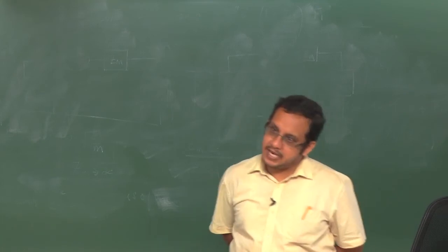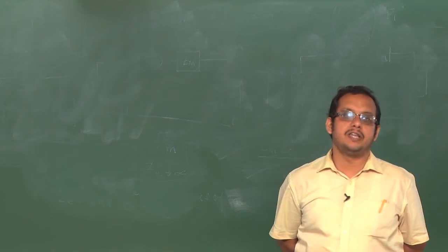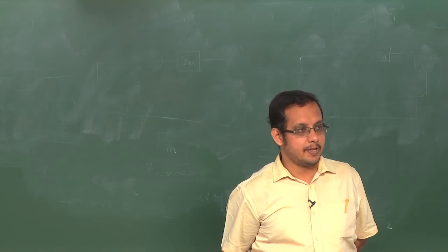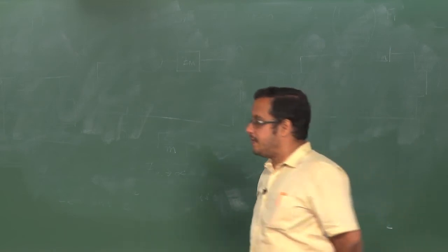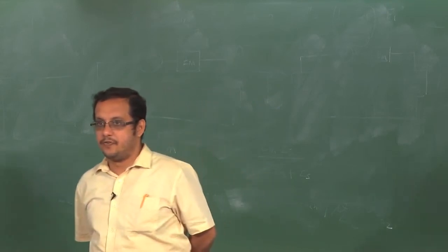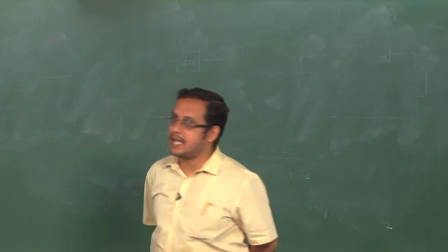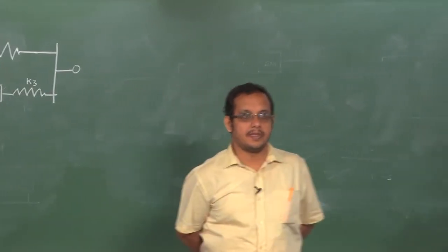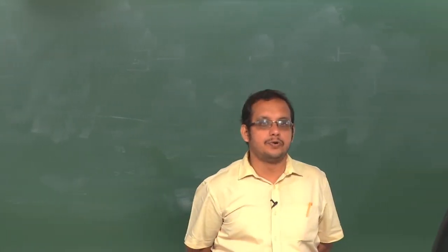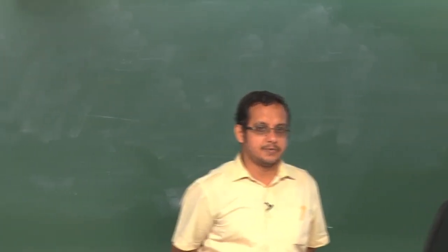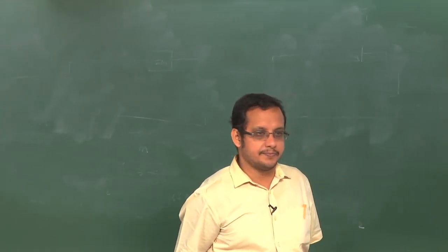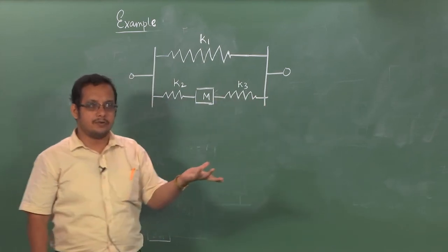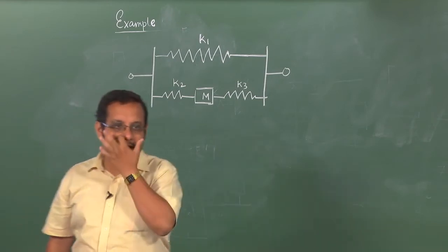If it was placed in line, then the forces between the input and the output port are possibly different, but the velocities are the same, right. And if it is in shunt position, the velocities are possibly different, but the forces are the same. What does that argument lead you to for this structure? Can we say anything about the input and the output ports in terms of equality of the forces and the velocities? Can you say for sure that F1 will be equal to F2 or V1 will be equal to V2? You can't, right. So, there lies the problem.